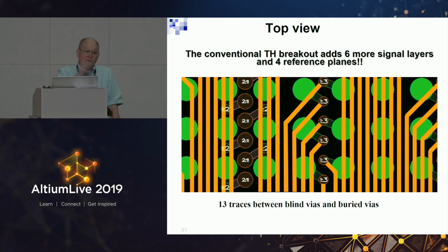So you can keep doing it the old way with 2 traces. I don't mind. But there is a mechanization where you can get 6 times more, which means you need fewer signal layers, which means you need fewer reference layers for those signal layers. And the multilayer collapses down to something that's easy to solder but more reliable. It's not as thick.